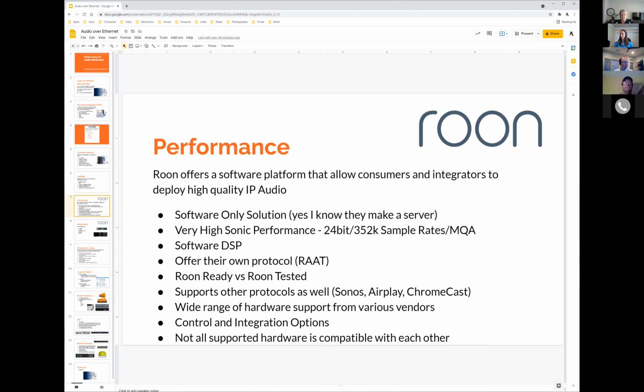The other thing to know about Roon is that in digital audio, there's a device that sets the clock, sets the pace of the audio, if that makes sense. And in Roon, all the endpoints, the physical players, have their own clock. This can become challenging. Roon works very hard to unify what's called network latency. So this is how quickly things start and stop. But the challenge is sometimes that audio can drift. So if you have adjacent rooms with two different players and you have a very long song, you may find that there may be a delay or an echo very slightly. The clocking gets resynced at the beginning of each song.